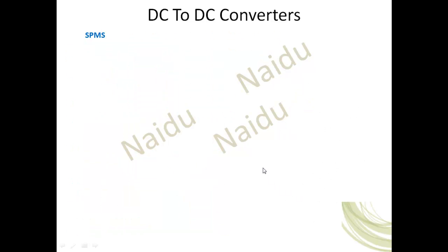So finally, I would like to discuss a few things in case of SMPS. Remember how to identify whether a given circuit is a buck converter, boost converter or buck-boost converter. There is a simple rule. If the inductance is connected on the load side, that means whether the main switch is on or off, the inductor is always connected to the load side, then it is a buck converter.